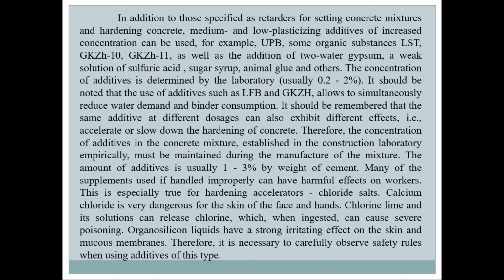The concentration of additives is determined by the laboratory, usually 0.2–2%. It should be noted that the use of additives such as FFB and GKZH allows to simultaneously reduce water demand and binder consumption.